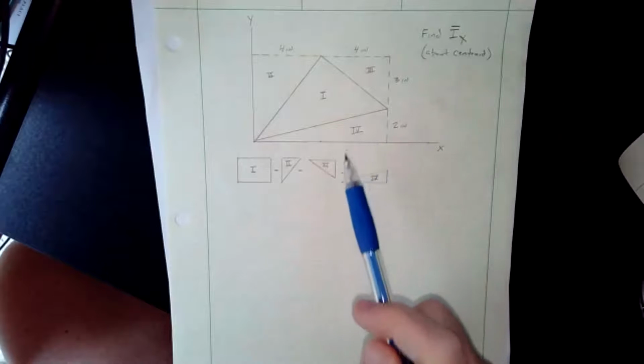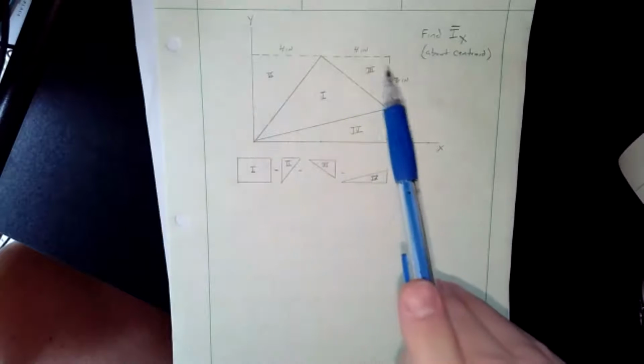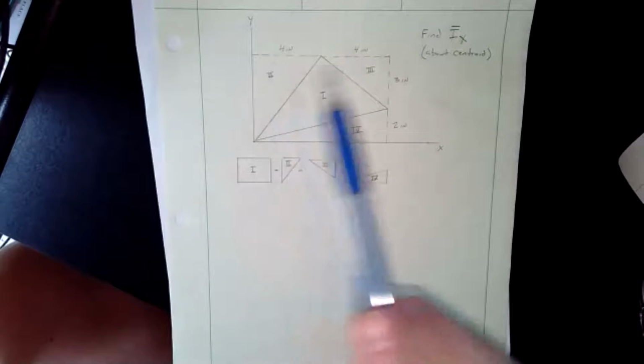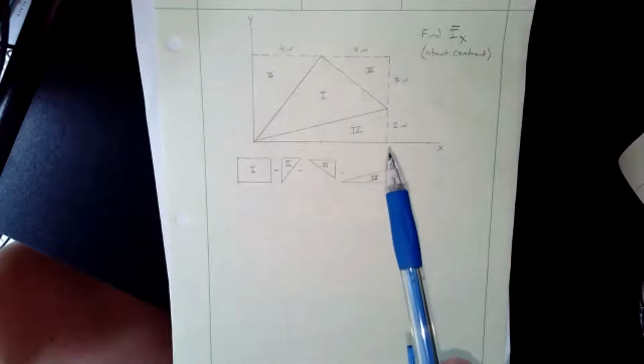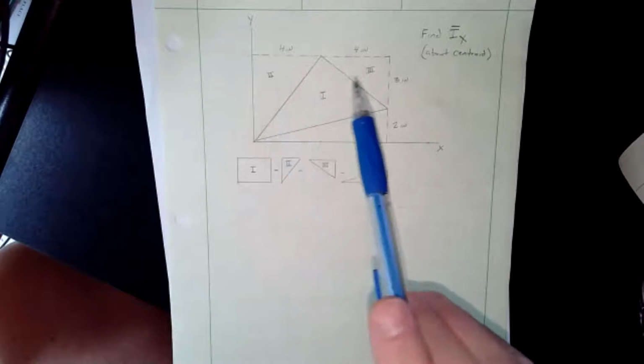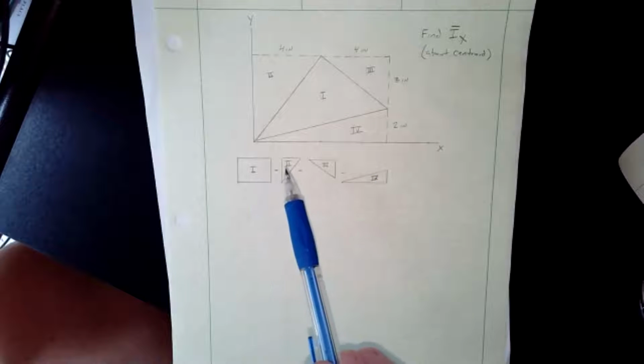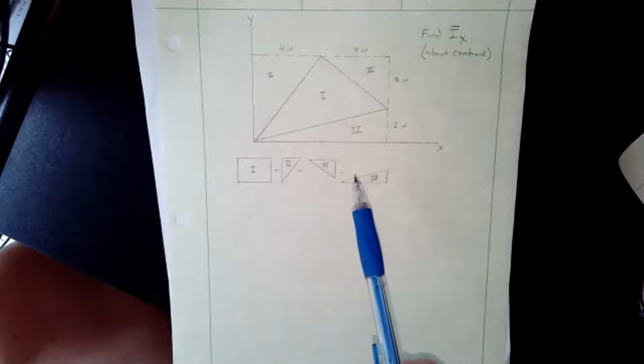So you have this shape. And so there's different ways you could approach this, but I think the easiest way on something like this is to find the moment of inertia of the rectangle, the 8 by 5 inch rectangle, and then subtract off the moment of inertia of these open spaces, which are just 3 triangles. So you have I2, I3, I4. And that's how I would approach problems like this.